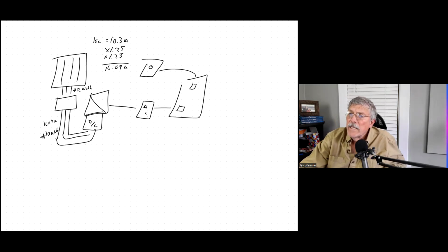So let's say that this is in a conduit and these wires are sitting here. Well, there's a couple of issues because they'll all be in the same conduit and they're lying on the deck and they're exposed to sunlight. So you look up and you find out that the hottest temperature ever experienced in this particular location is 38 degrees Celsius. But because they're lying on the roof, we've got to add 33 degrees Celsius.